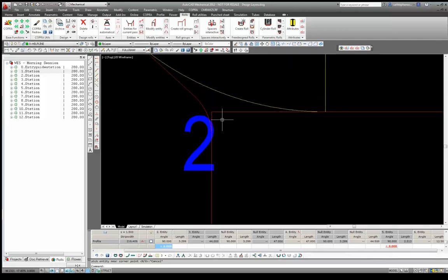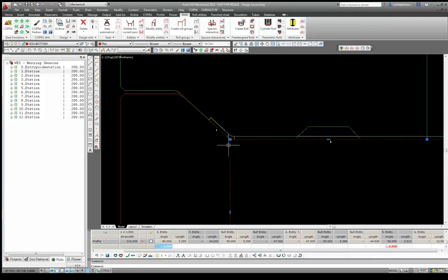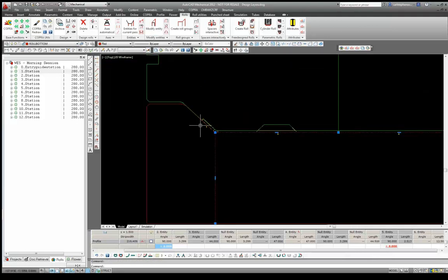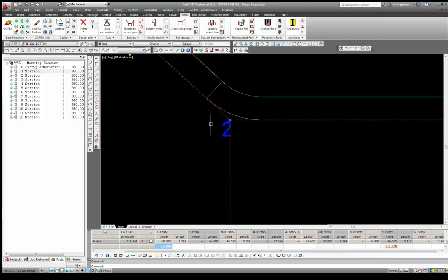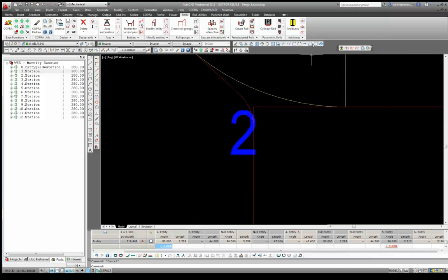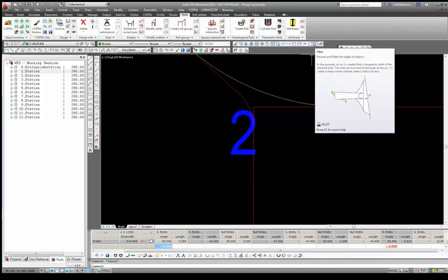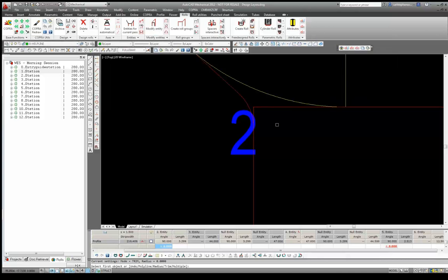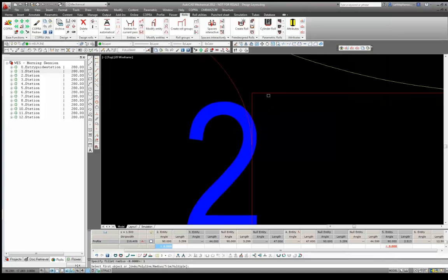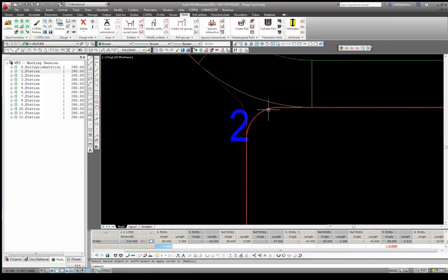So you may recall this is a polyline we split and created two individual flanges, mirrored and joined. So now I'll go here to the AutoCAD fillet command, specify the fillet, again an R1, and I'll fillet this line to this line. And you can see our polyline now.